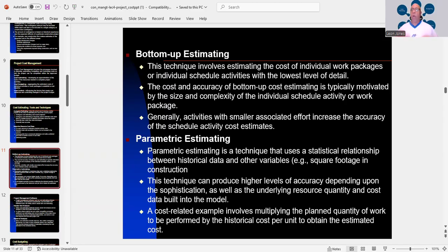Now, when I go and estimate that, I'm going to use a unit. That's what they're talking about. So I'm going to end up with square feet. I'm going to multiply 20 feet times 40 feet, and I'm going to come up with 800 square feet. That's what they're talking about. And there are going to be items associated with the materials to place that concrete slab.